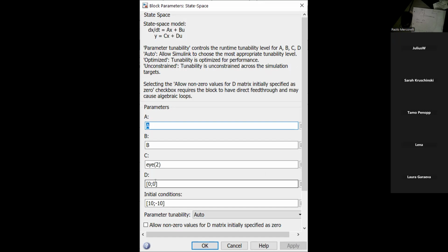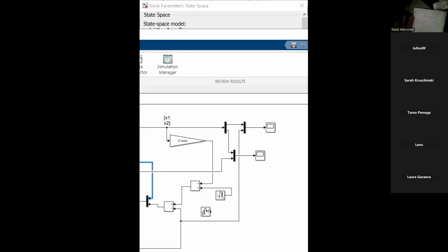Basically, you can copy the matrices A, B. Now do we need B for the observability? No. But of course, if I have an input here, to test, we have to have information about the input because it's something which moves the system. The observability is independent of B, excuse me. But of course, if I have a B, this means if I have a U, U goes through the system thanks to the matrix B.